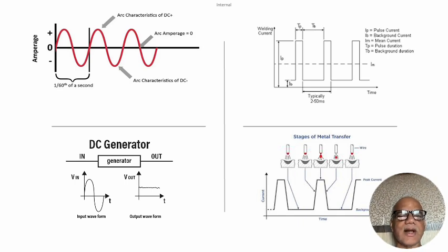So this is one important characteristic of the current. From a sinusoidal wave, we convert that into almost flat DC, or up to 2% ripple. Most of the welding processes accept the ripple factors, and that is easily possible using a very old thyristor or bridge rectifier technology, or electronically nowadays it is possible to do even better than the 0.2% ripple factor. Similarly, what we are converting here is the same 50 or 60 cycles per second, that is the 50 hertz frequency of our electrical systems.